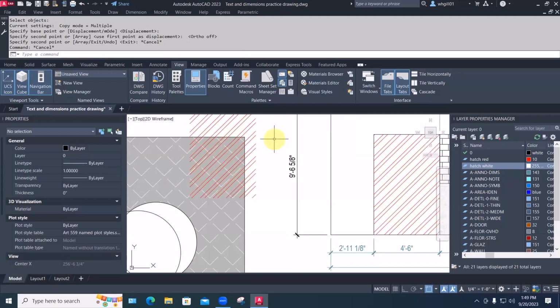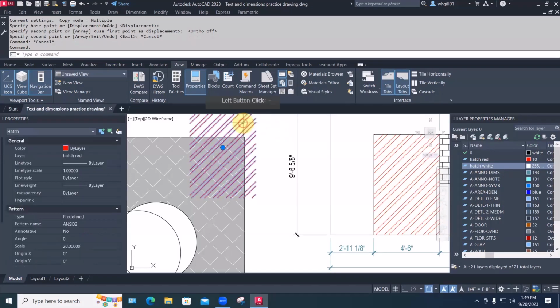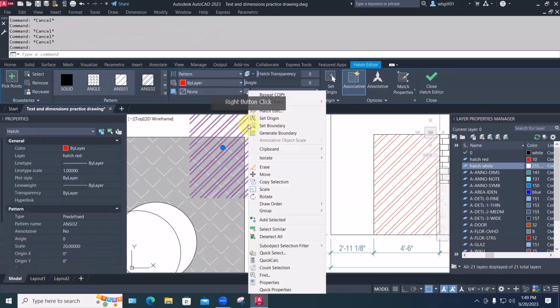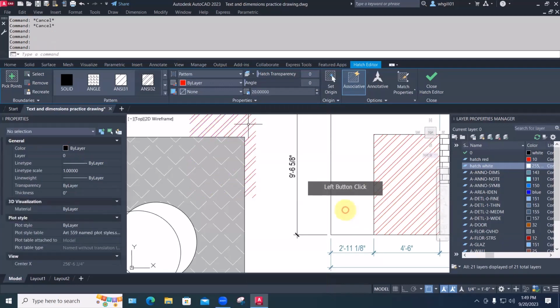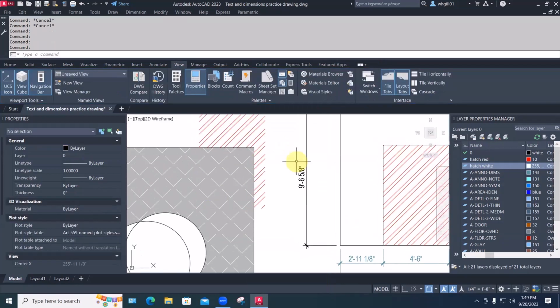And right now, it looks like we have the red sitting on top of the gray. AutoCAD always puts anything that's new, I just created this hatch over here, visually on top of what's been there before in what's called its draw order. And if you want to reverse that, we can select the object. Let me see if I can just right-click it. Draw order right here. Select an object and right-click it. And then I can say bring it to front, which is basically sitting on top of everything else visually. There's no actual 3D separation going on. It's just how this gets processed visually. Or I can say send to back. And now it's behind that gray stuff.